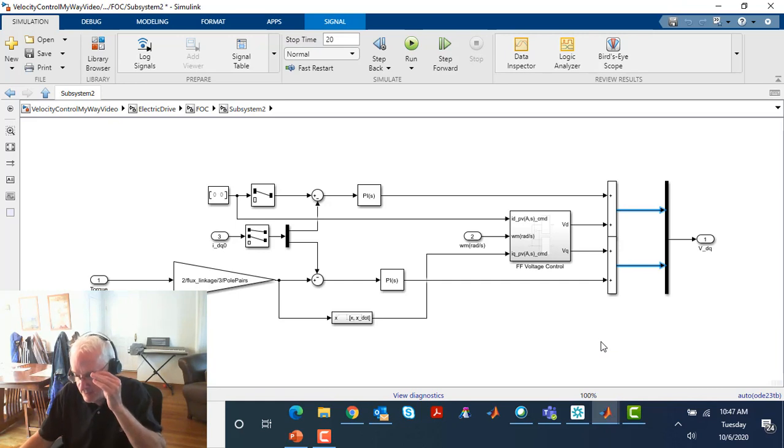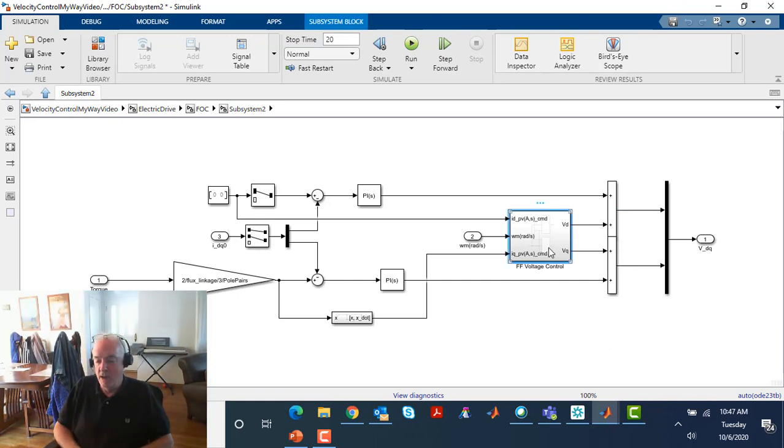Okay, and it's because I added this piece that I believe we get this whole thing to work so well. And all I'll say with regard to the feed-forward idea is that it is, again, taking what you know and understanding these dynamic equations of voltage and current response, expressed in this DQ reference, to come up with a better understanding of how we want to vary our voltage, right?